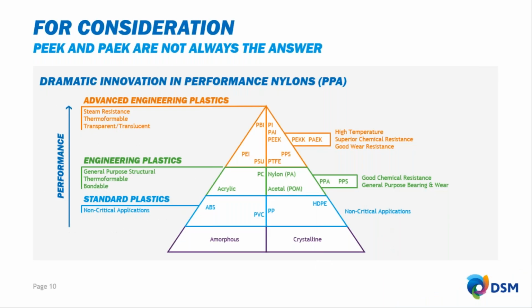Yeah, and going back to the pyramid here, as Mitchell touched upon our product portfolio from DSM, I'm going to take a slightly different approach, looking at what materials lend themselves to the oil and gas industry. On the right-hand side, the crystalline materials really are the key focus for DSM, and for the oil services and the energy producers, that right side of the pyramid is extremely important because it's the crystallinity of the products that gives the performance, whether it be temperature, chemical resistance, abrasion, and wear.